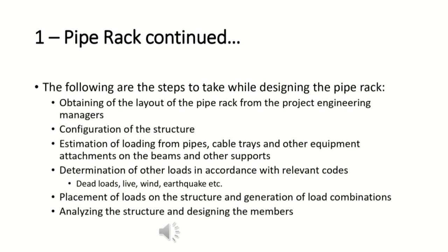The earthquake load is important in case there is such a tremor in the future of the project, so that the adverse effect does not bring the whole pipe rack system into jeopardy. 5. Placement of loads on the structure and generation of load combinations. These load combinations have been recommended by the different codes of practice as they help to identify and estimate the most adverse combinations that will give you the highest loading on the structure. 6. Analyzing the structure and designing the members.